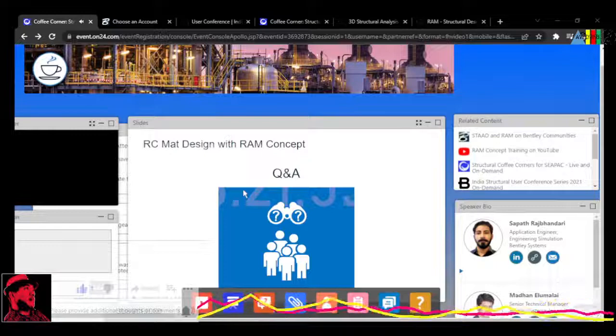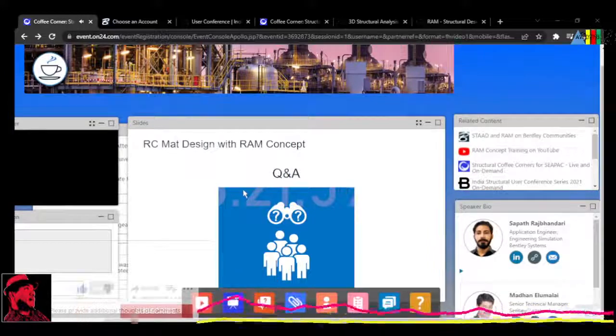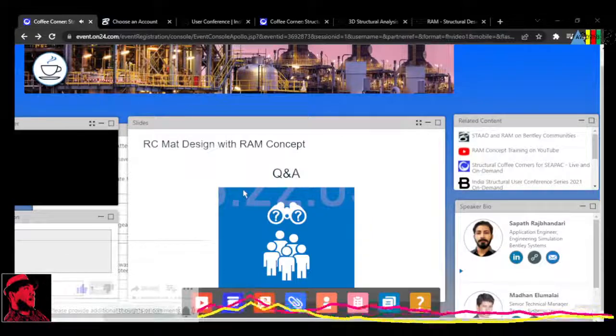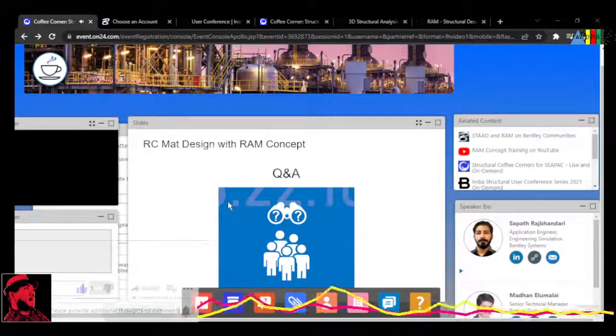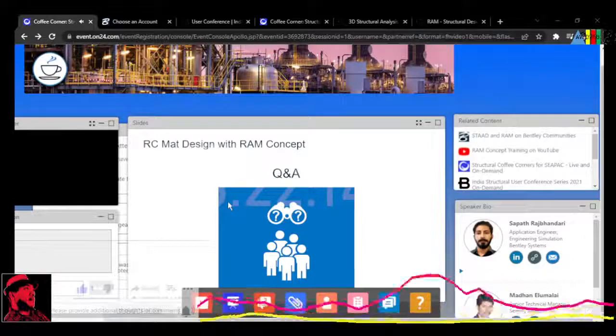The code slab will use slightly different rules, although the rules can be set the same in the code slab as well, but the reinforcement design is done separately for the area of the slab closer to the support and around the middle of the slab if you select the code slab option, whereas for the full width it's the same.